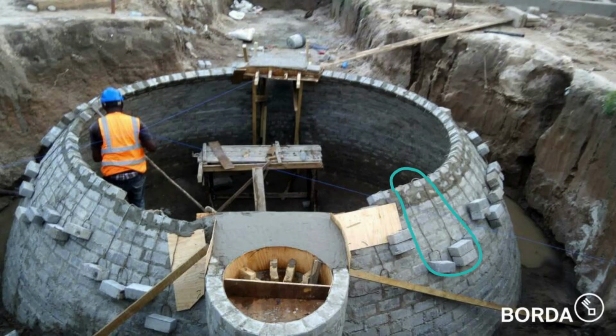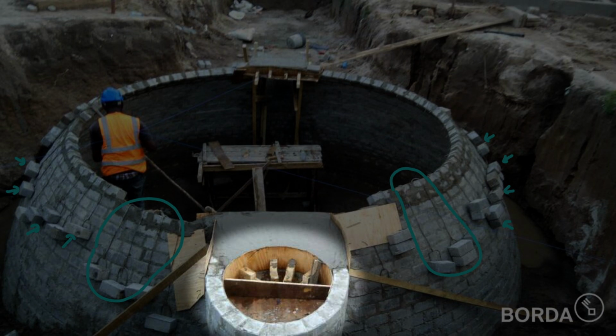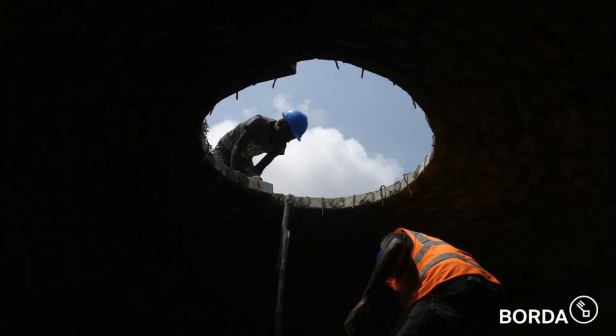The secret to the building of a dome is to hold the bricks in place with special hooks until the mortar dries a little, or until the layer is complete, as shown here. Here we also see the element which will function as inlet of the feedstock. These layers of self-supporting bricks placed on top of one another enable us to build the dome as freestanding without using any sort of frame.